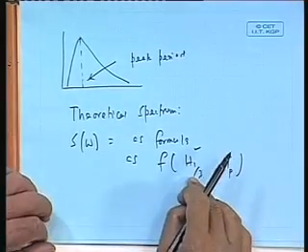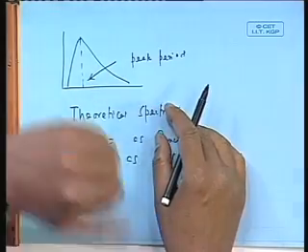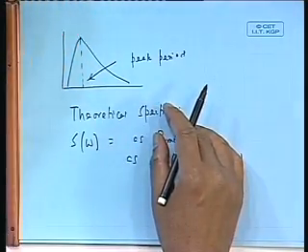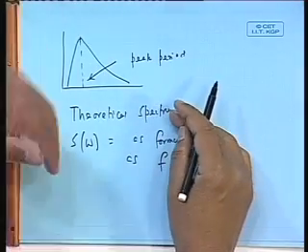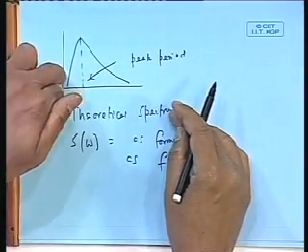Why does this H 1/3 come in? See, supposing there is a wind blowing stronger, then obviously you would expect rougher weather. Rougher weather means it would have a higher significant wave height. So conversely, if I have a certain place with a significant wave height of 5 meters, then I can go back to the spectrum and put it into this formula.